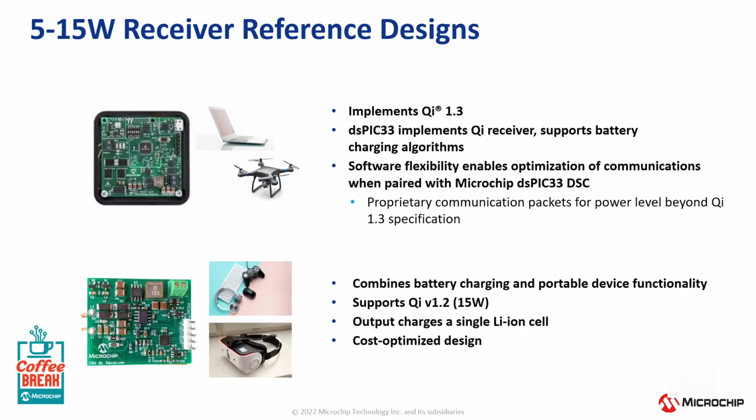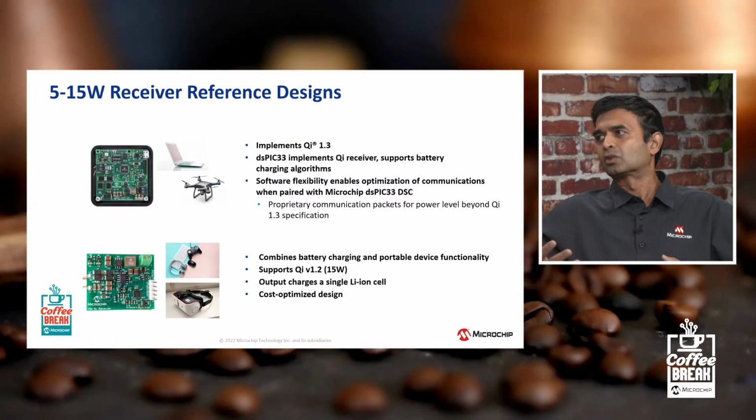So in addition to just the Qi 1.3 implementation, also the somewhat flexible design that this is enables increasing the power levels to beyond 15 watts that the Qi 1.3 specification supports. And also you can add additional algorithms if you have any battery charging algorithms or anything like that, that can be added on to the controller as well.